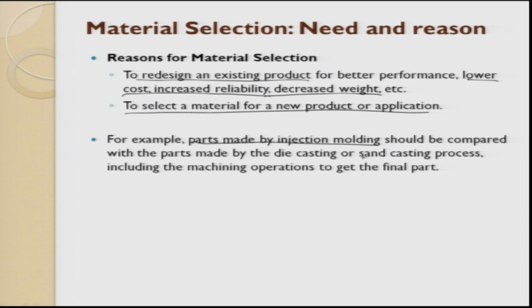One is the casting process, it can be made by the die casting process, or today they are looking at the injection molding process. So in the injection molding process, polymer is used, and the carbon fibers, I said the carbon fibers can exist in several forms. So they try to make a three-dimensional reinforcement and inject polymer into it, wherein they are also thinking of placing a location for inserts. So this is what it is.